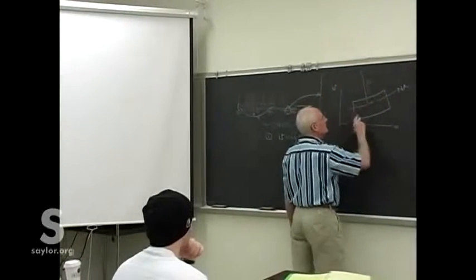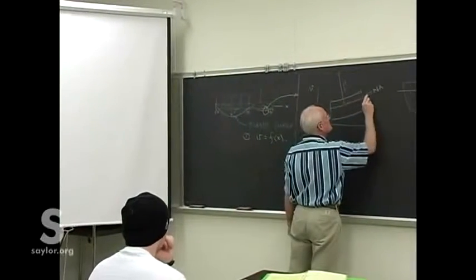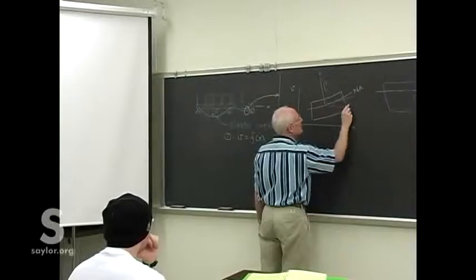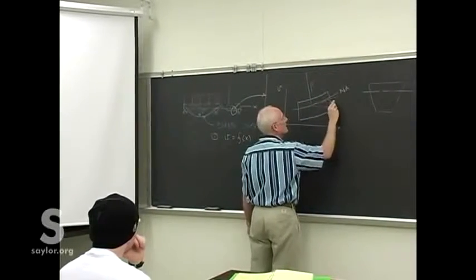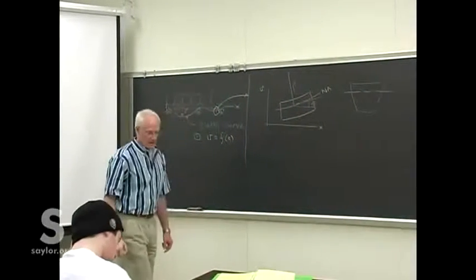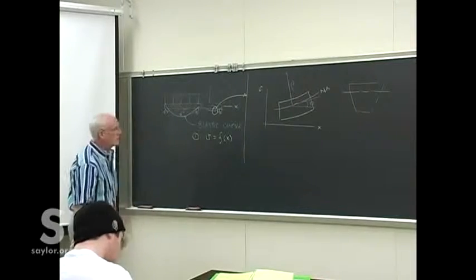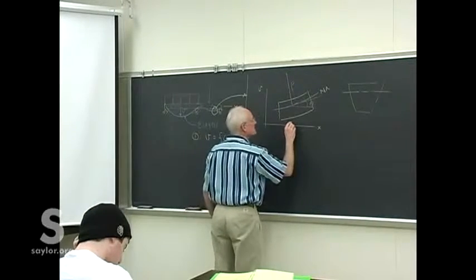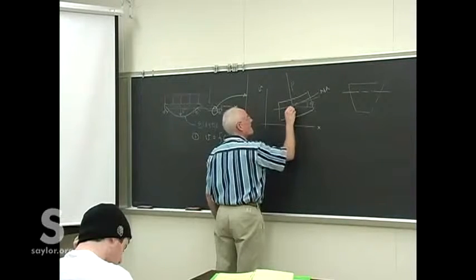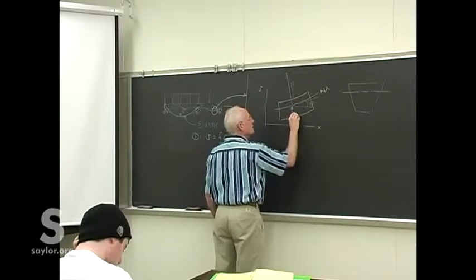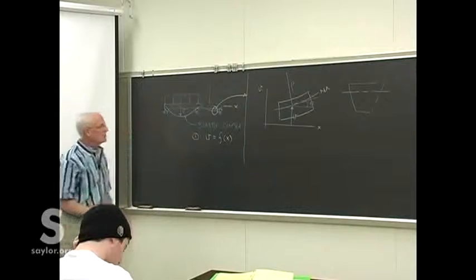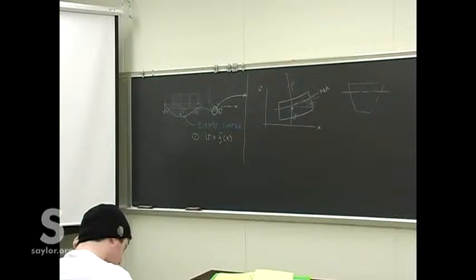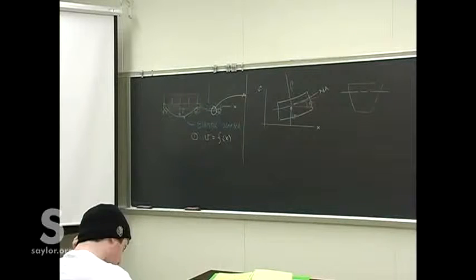So we've got the curvature there. At that same spot, we've got some slope to the curve of that place, and we'll call that theta. So we're bringing together then this deflection from the neutral axis, V, and we're trying to find out the equation for that as we go along the beam.